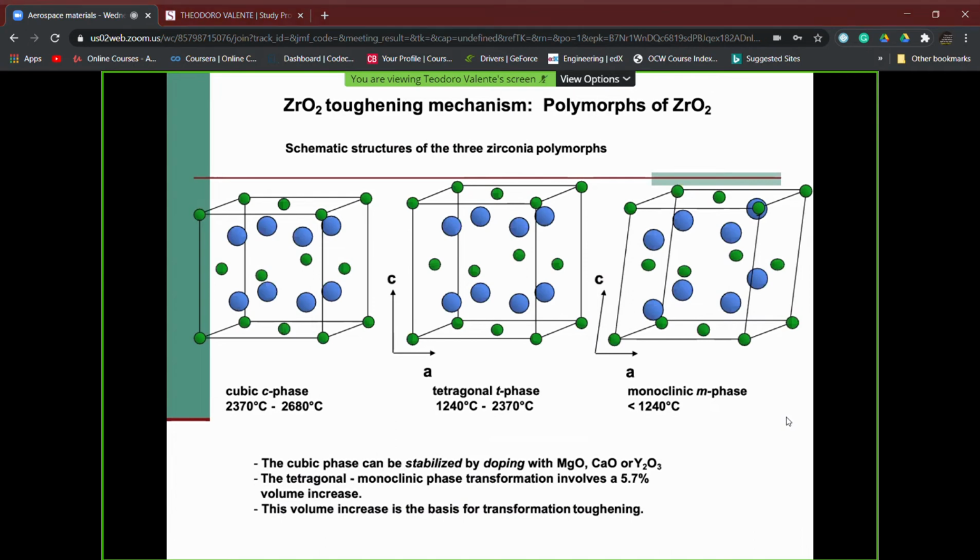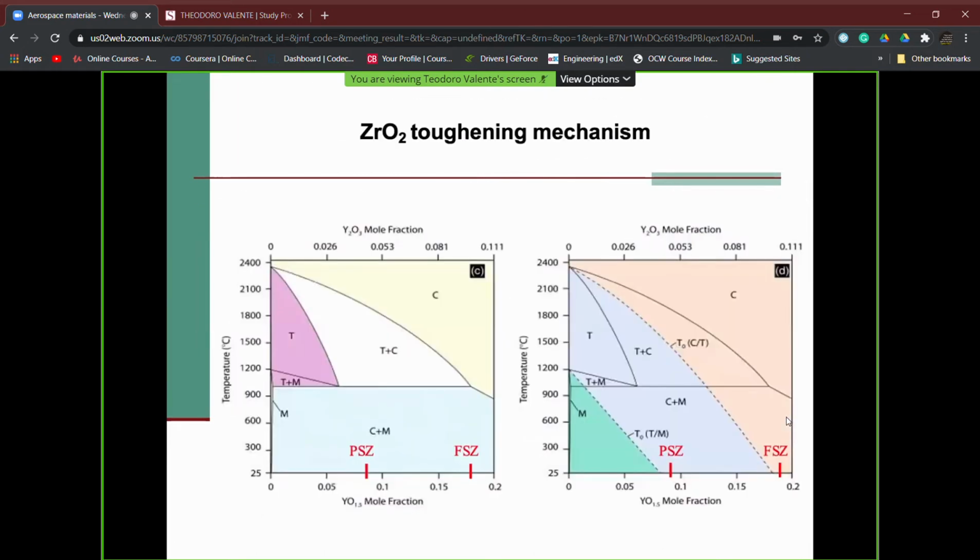oxide. And so when we are going to put together zirconium oxide with yttrium oxide, in order to understand what is going to happen in terms of thermodynamical stability of the phases, we need to look to the phase diagram. They are binary phase diagrams in which we do not have on the vertex here and here the elements like in metallic alloys, but we have the compounds.